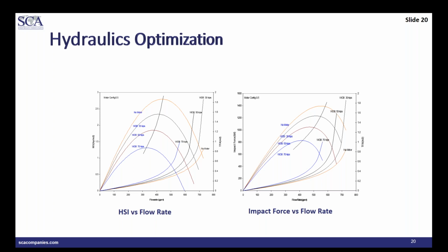So it is completely different. Most of the time we use the same mechanical specific energy calculations, but it is dependent on the pressure drop, the torque, where in a regular one it is purely a mechanical torque. Now this is dependent on the hydraulics of the mud motor. So that we need to clearly understand, which will also be covered in the class.